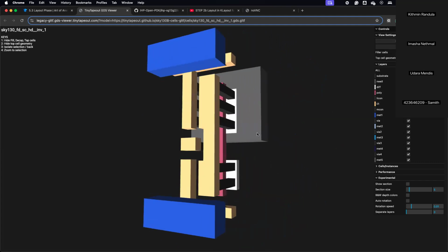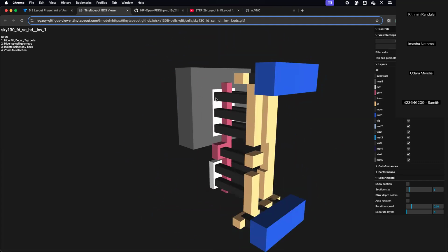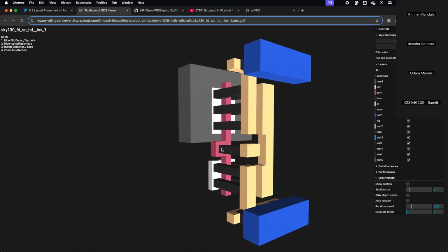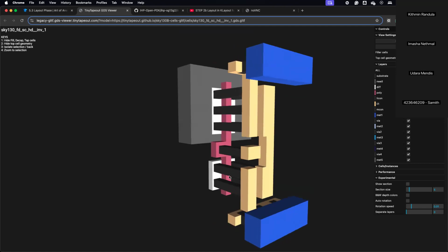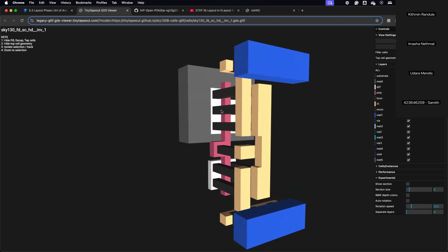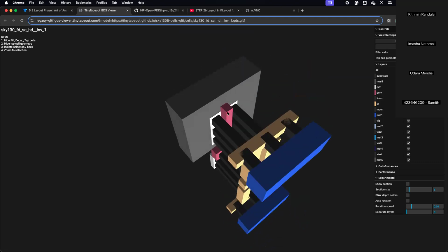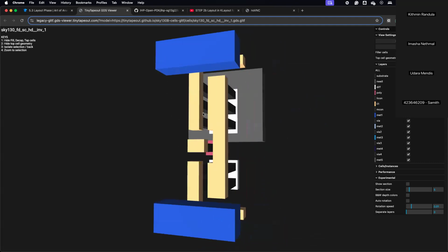active areas. And on top of the active area, you can see the polysilicon gate that is creating the gate. So the active area is separated by the polysilicon gate, and the polysilicon gate is controlling how much is traveling between these two areas. And you can consider one side as the source and one side as the drain.